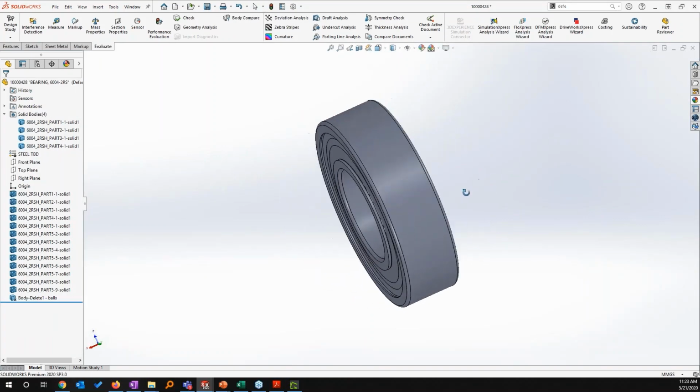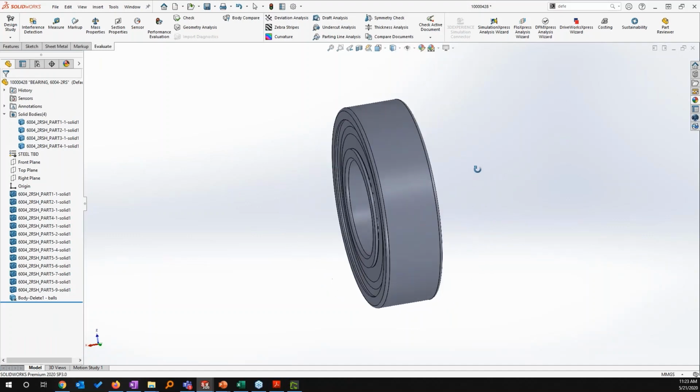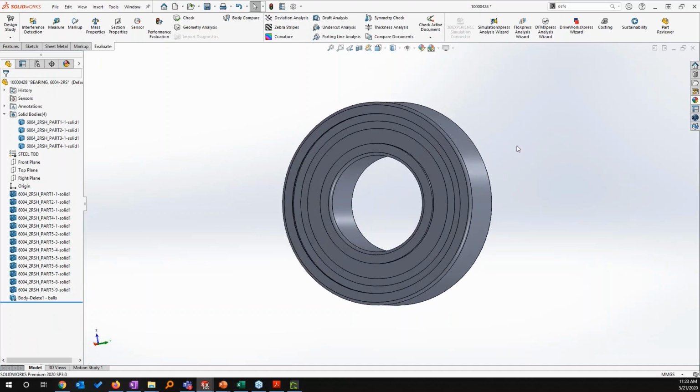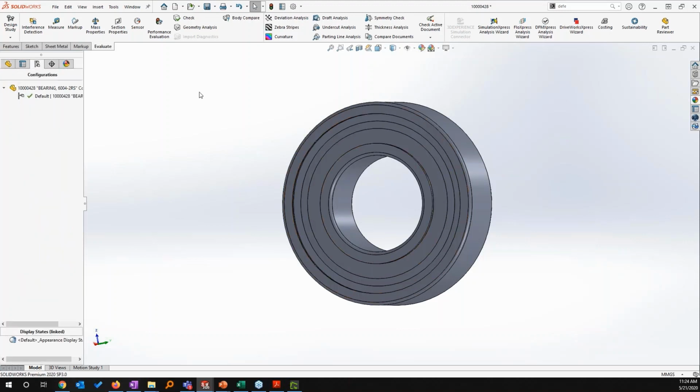Looking internally, we've got some internal surfaces, some faces, but when we're working with an assembly, do we really care about all the different internal geometry? I would wager that at times you do not. That would mean that there is a place for a defeature tool. This is a tool that you normally use to take a component and reduce its complexity. It's a built-in feature. You can look for it in your command line here.